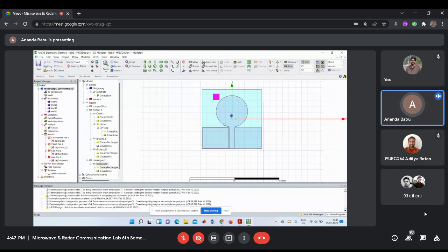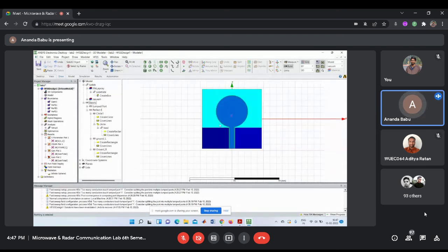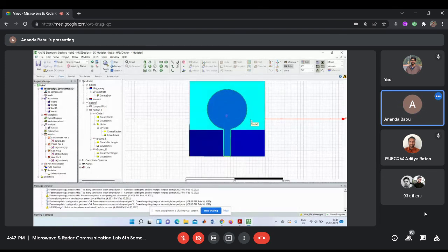We recently got one. So here it shows very small rectangle boxes. We can place small rectangle boxes in different places. Suppose two rectangular boxes here, two here. Placing any additional shapes in this patch automatically increases the bandwidth, the gain, and the resonant frequencies. So I am saying simple designs. Understood?